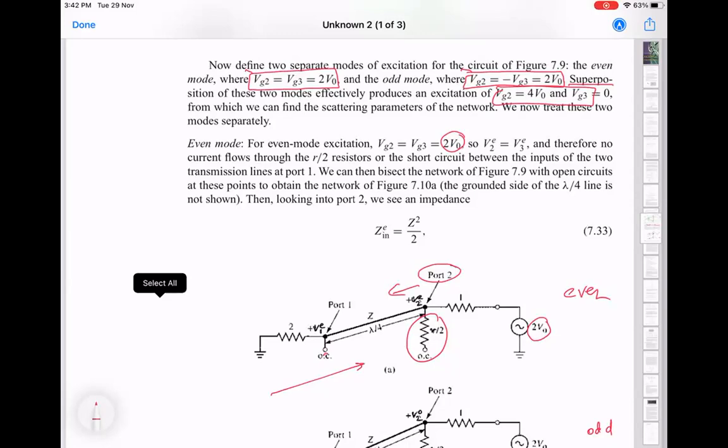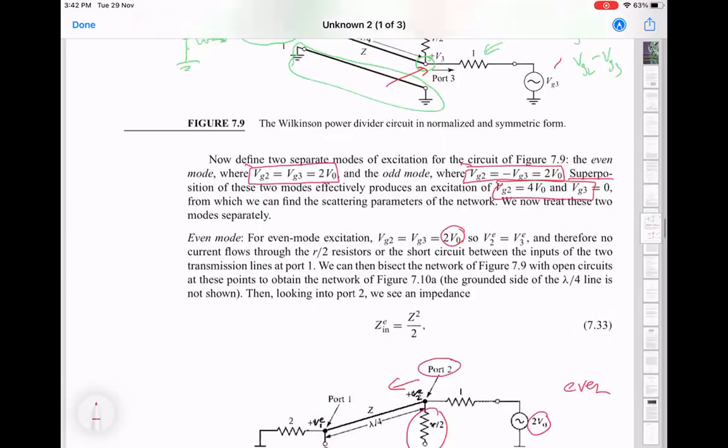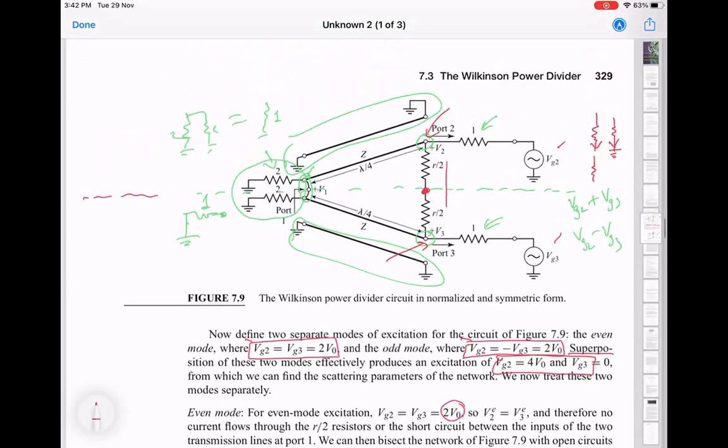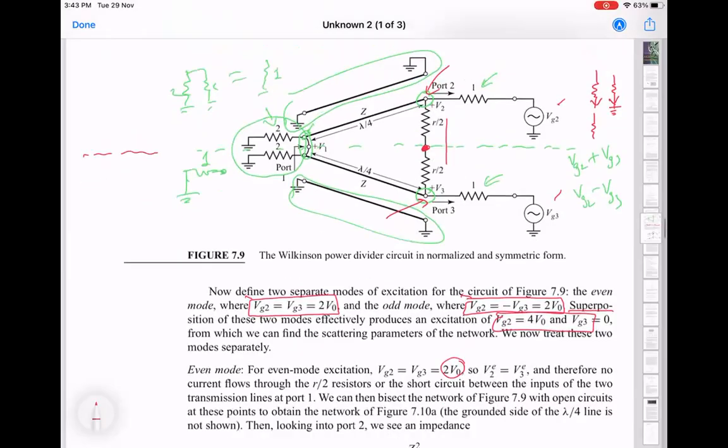You have a 2 ohm resistor. And again, if you forgot from last time, we had normalized these resistors, so 50 ohm becomes 1. This is a 100 ohm resistor because we had separated the circuit into 2 halves. And we put 50 ohm and 200 ohms in parallel, which gives you 50 ohms, right? So that's how this became 2 here.